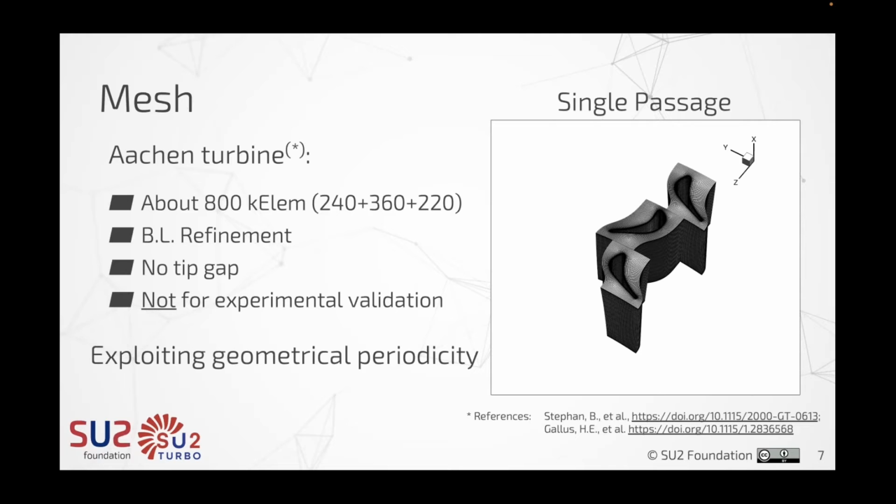So generally speaking, turbomachinery has a gap between the end of the rotor blade and the upper surface, the casing of the machine, which is needed, of course, to prevent disasters from occurring, because we need to always make sure that the blade doesn't touch the casing. There are cases where you have some sort of additional surface enclosing all blade passages, but still above that you would have some clearance to guarantee that the machine runs safely and doesn't touch the casing.